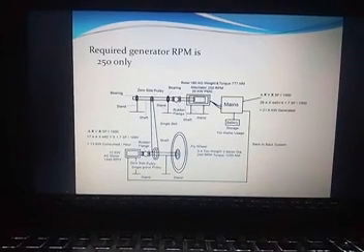So this is the diagram which we have discussed earlier. If you understand this diagram, it will give you a lot of information about the flywheel: the mass, the diameter, the RPM. Here the RPM, the mass and the diameter are the deciding factors for the torque, which should be greater than the torque of the alternator connected to this rotating system, that is the flywheel. The torque of the alternator is 777 Nm. The torque of the flywheel is 1250 Nm.